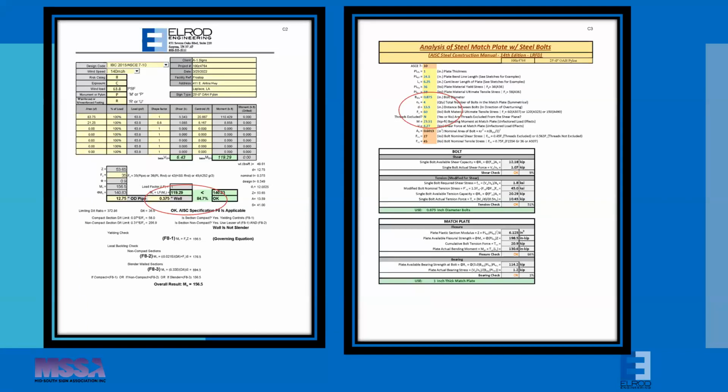On the left of the screen, this is where we're analyzing the pole, and you can see that number circled, 84.7%. What that's telling us is that we're comparing the forces that are applied to the pole versus the allowable maximum stress that can be applied to the pole. That's not the ultimate stress, and that's a rabbit hole we don't want to go down right now, but the allowable stress. So you're seeing 85% of capacity, that's really in a good spot because you don't want to run up against 99.9% of the capacity because there's no margin for error.